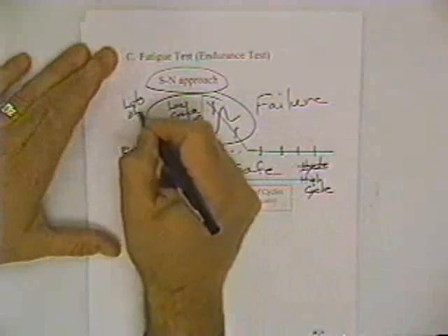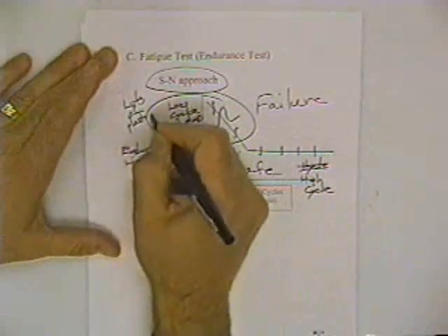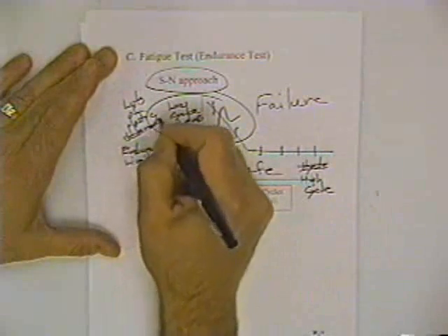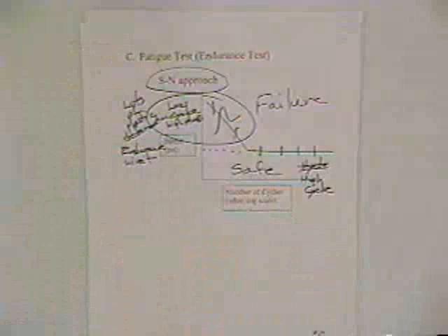Lots of plastic deformation on each cycle, or there can be. Under low cycle fatigue, materials can fail at stresses below their yield strength, but because of the cyclical nature, you can induce a crack, the crack can grow, and final failure will occur.